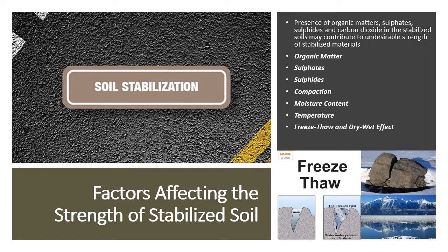Stabilized clay soils are more likely to be affected than other soils due to alteration of the plasticity properties of clay. In contrast to cement, delay in compaction for lime-stabilized soil may have some advantages. Lime-stabilized soil requires a mellowing period to allow lime to diffuse through the soil, thus producing maximum effect on plasticity. After this period, lime-stabilized soil may be remixed and given its final compaction, resulting in a remarkably higher strength than it would otherwise have.